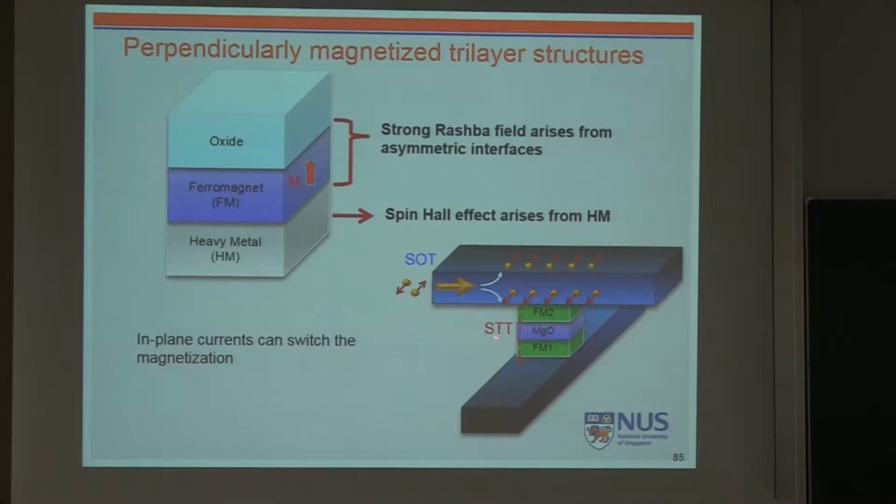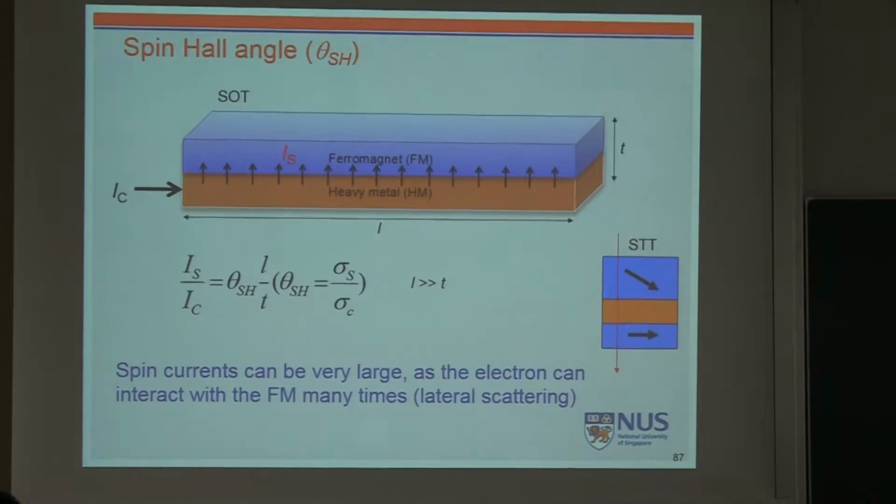In a conventional spin transfer torque device, we have to apply current into the cell, and in order to switch, we have to apply a lot of electrons. That damages the MgO, and also gives some instability, all kinds of issues in terms of device operation, and reliability was also a big issue. But SOT solves all these problems because we apply current along the metal line, and the metal line is much more stable than oxide or any other semiconductors.